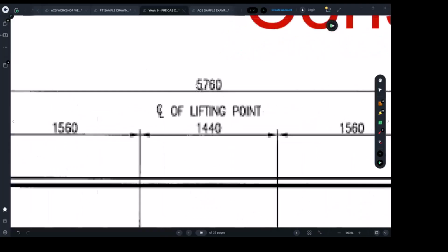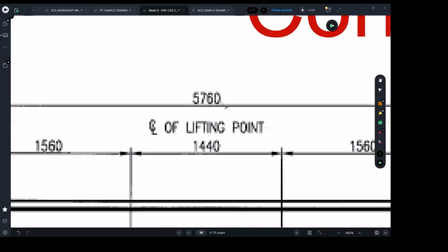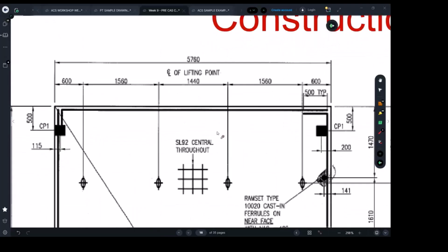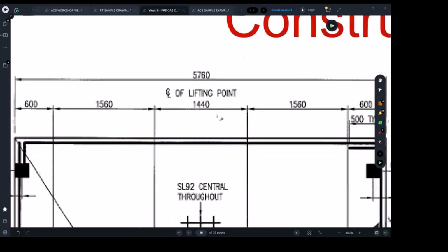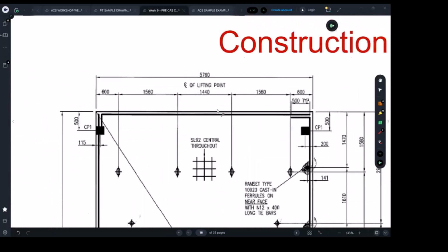And maybe the next panel was different, so someone will ask, but doesn't the full length of the wall need to be correct as per drawings? Yes, that's right. Some panels may be longer by 60 mil, but the other ones will be shorter by 60 mil. So that will work out to the final correct position, to the final full length. But the shop drawings are going to give you almost the buildable correct dimensions.